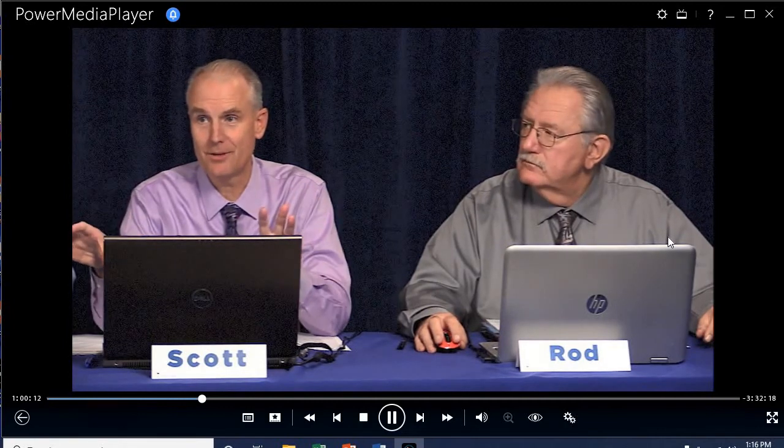Hold on. You're telling me because the fire pump is a phase-to-phase load, we're not bringing a neutral to the fire pump? Correct. So since there is no neutral going to the fire pump, that means there's no neutral at the transfer switch, which means that that generator now is a separately derived system. Automatically. Yes. And then we have to do things if that's the case. Okay. So where people get messed up is if they have a 3-pole solid neutral transfer switch and a fire pump, now you're in trouble, because one you have to be separately derived, the other you're not. So that gets very tricky for people.